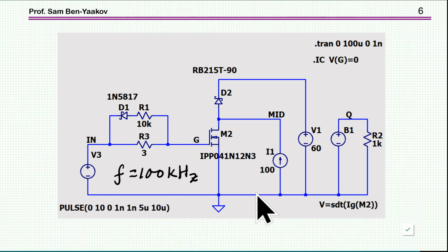So now let's see, first of all, if the model of the transistor, the LTspice model, really holds up as far as this charge goes, because we are going to use it later on. So therefore, I'm going to examine the amount of charge that goes into the gate. What I have here is a pulse source, which is representing the driver, high and low. It's 100 kilohertz. I have two resistors, but as you can see, I'm just using this 3 ohm. This one is blocked just to simplify matters. The resistance is much larger, so we can neglect the current here.